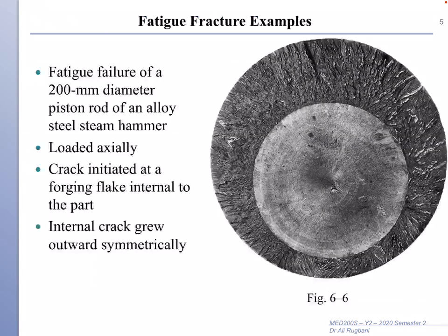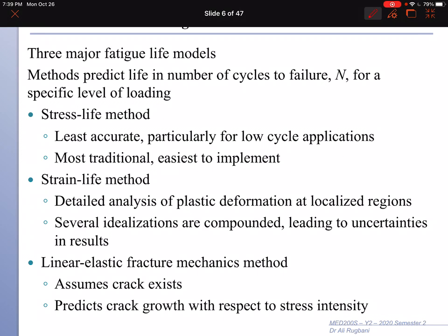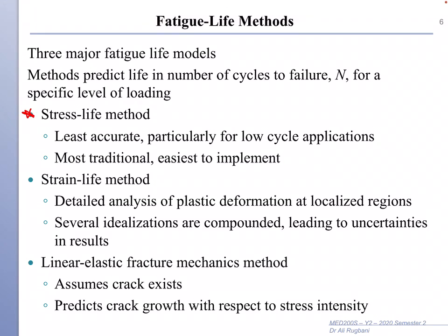Okay, so we need a method to study or to simulate fatigue failure when we have variable loading. We have a few methods, but in this course we will study the stress life method, which is a simple, most traditional and easy to implement method. So in this method, we will link the amount of stress with the number of cycles we can apply that stress before failure.